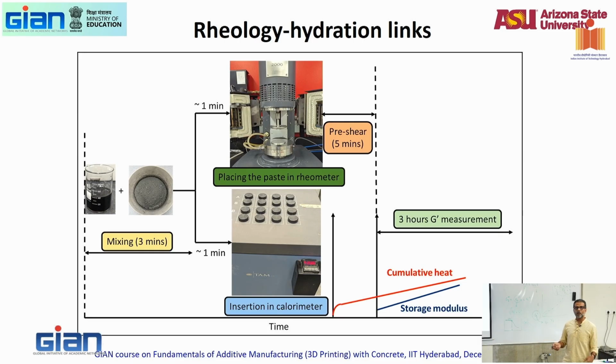So you do rheology, you get all the rheological parameters, you get hydration. Hydration and rheology are connected for all the reasons that we talked about earlier. Rheology is about particle linkages, particle connections. Hydration happens much more when the particles are connected more, and when the particles have started to develop the interconnected network, and hydration proceeds, rheological characteristics go down. So you can really get a good relationship between rheology and hydration.